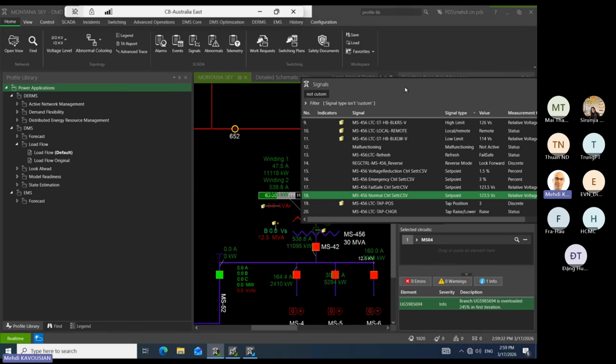In the distribution substation, we have a voltage regulating relay. So if I set the set point on the voltage regulating relay, it can automatically control the tap changer to keep the normal voltage for this electrical system.